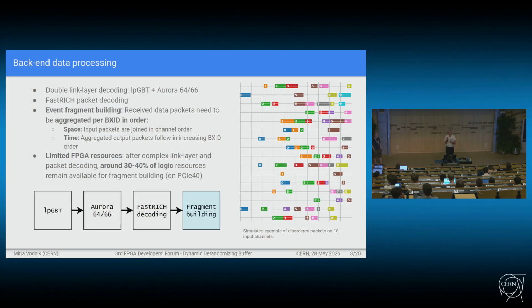Sorry, I don't understand. So, for example, I have TimePix4 in mind. You receive data on different links, and the data are not ordered, but you don't have a bunch of data. Basically, each 64-bit word encodes its own time of arrival in the detector. Okay, but it has a kind of timestamp.